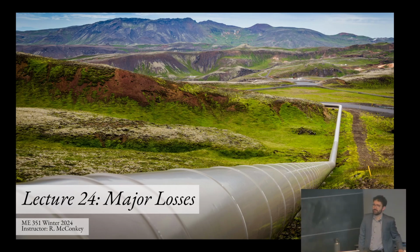Major losses are basically the dominant source of pressure loss and frictional loss that we need to make up for in this flow through the use of pumps. And as a consequence, those pumps take a lot of energy. So one of the biggest expenses for a lot of these utility companies is just basically paying the electricity to power their pumps. So that's why we should care about major losses.